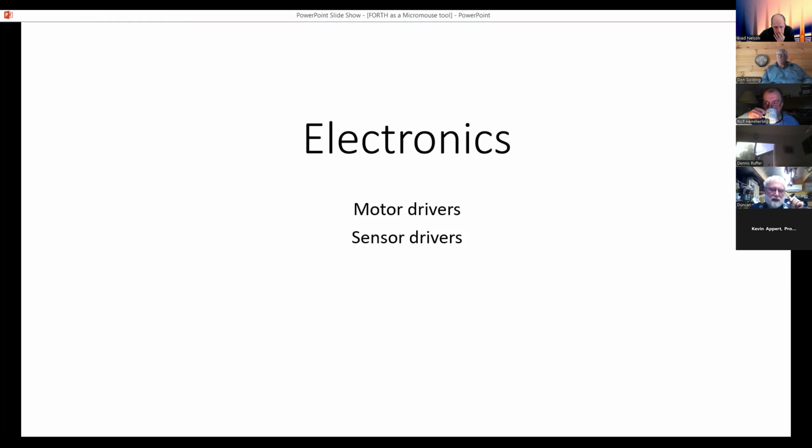Right, this kind of reflected light sensor can be quick. If you use fast sensors, fast ADC and good electronics, you can make a measurement in 10 microseconds or so. Poor electronic design, sadly an awful lot of people have this, can make the readings dependent on the time between readings and any variation in the execution time of the reading routine. You turn the LED on. If the electronics is not accurate, the brightness of the LED will be dropping with time as it discharges the storage capacitor. You're using a phototransistor as the sensing element.